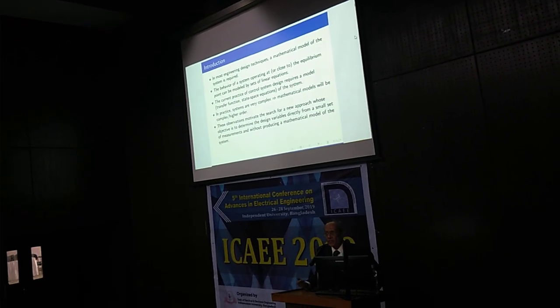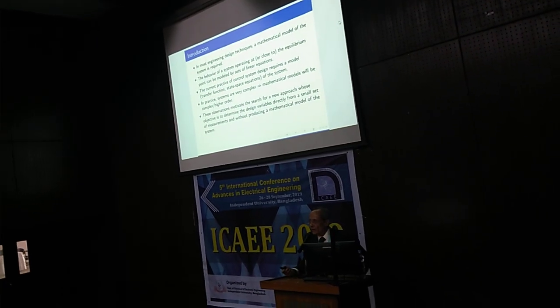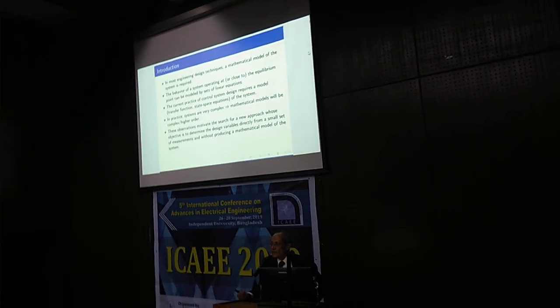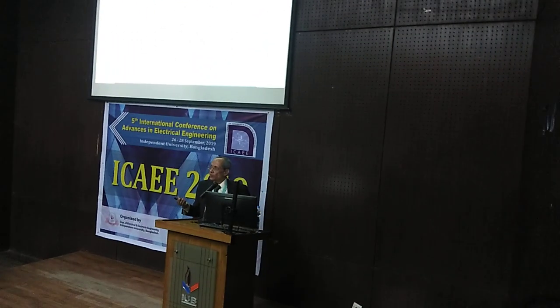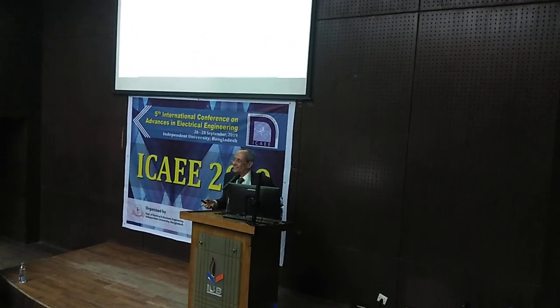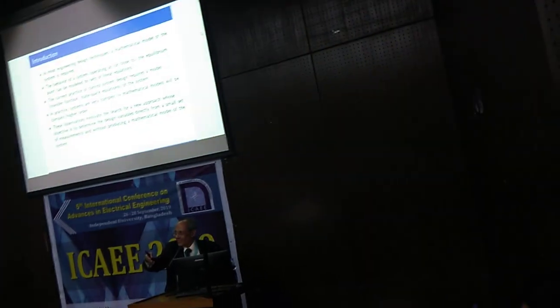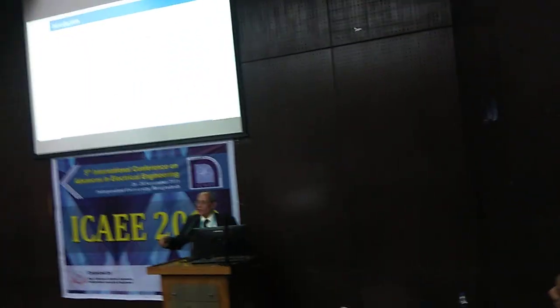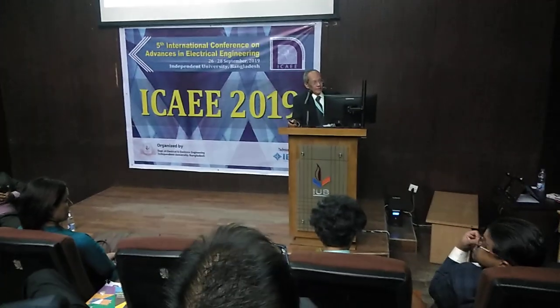In practice, systems are very complex. And one example that I like to give is there is a hydraulic network supplying water to a city, and you want to add another pipeline. How are you going to add the size so that a certain amount of flow occurs? You don't know what is existing. You can solve this kind of a problem with a few strategic measurements. All right.